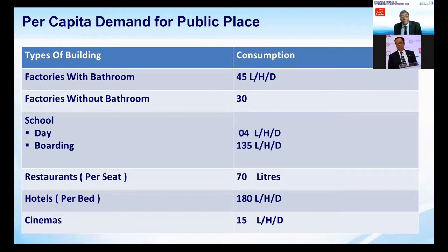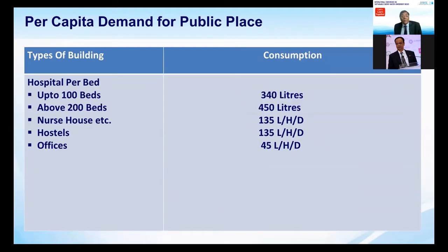In a restaurant, we take 70 liters of water per day per seat, per dining seat. In a hotel, per bed, we take 180 liters per head per day, and for cinemas, 50 liters per head per day. And now we come to the hospitals.